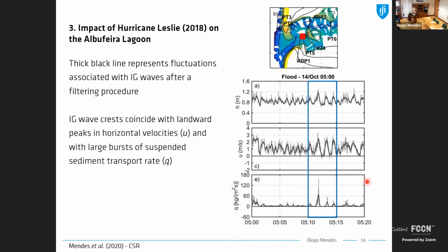Infragravity wave crests, so if you look to that time period, between 5:10 and 5:15, so within the time period of 5 minutes, you see that infragravity wave crests coincide with landward peaks in horizontal velocities. So this crest here coincides with peaks in our horizontal velocities and also with peaks in the sediment transport rate.